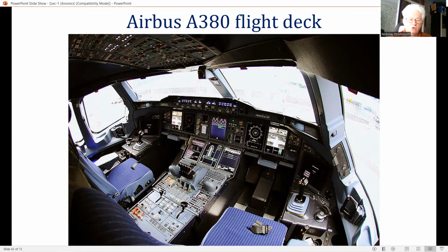The optimized layout of the multifunctional displays ensures that each of the two crew members can easily assimilate all relevant data, the screens being sized so that no eye scanning is necessary. In front of each pilot is a primary flight display and a navigation display. The remaining two screens display engine and system data. The pilot side stick controllers can be seen at the sides of the flight deck.